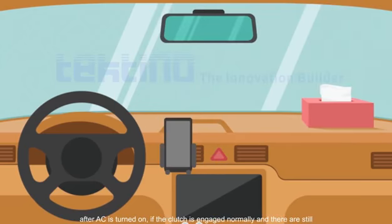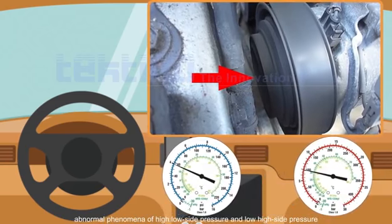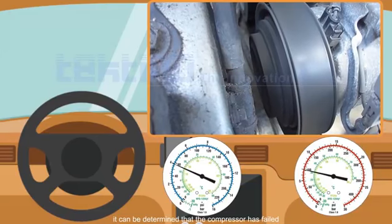After AC is turned on, if the clutch is engaged normally and there are still abnormal phenomena of high-low side pressure and low-high side pressure, it can be determined that the compressor has failed and needs to be replaced.